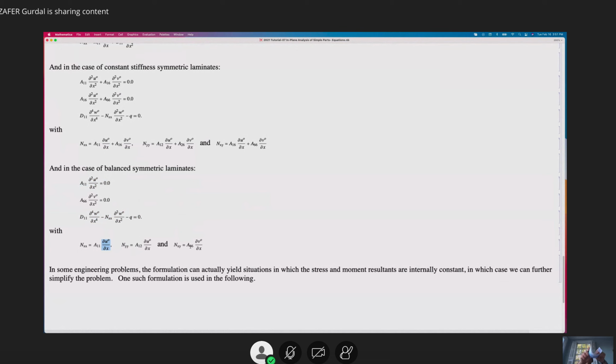And to bend it into a cylindrical shape like this, we are putting an out-of-plane force Q, which is shown in here, and bending it like that. So you can have a simply supported laminate here, bending like this, and we can also assume there is no movement in this dimension, so we can solve a plane strain problem like a beam.